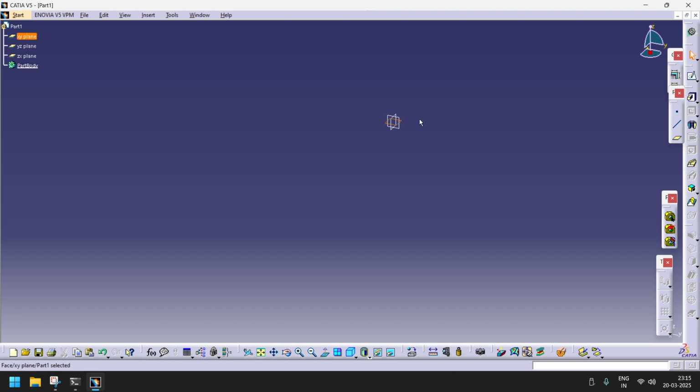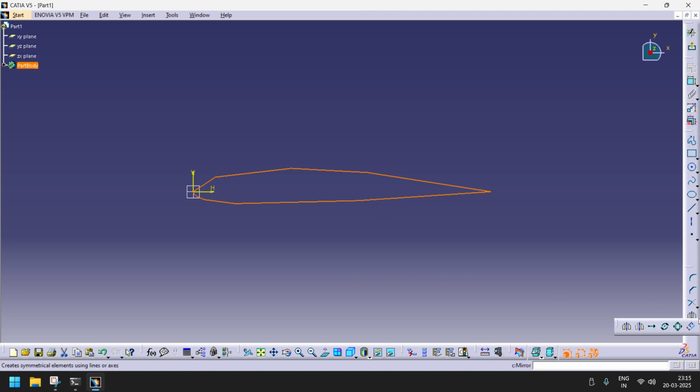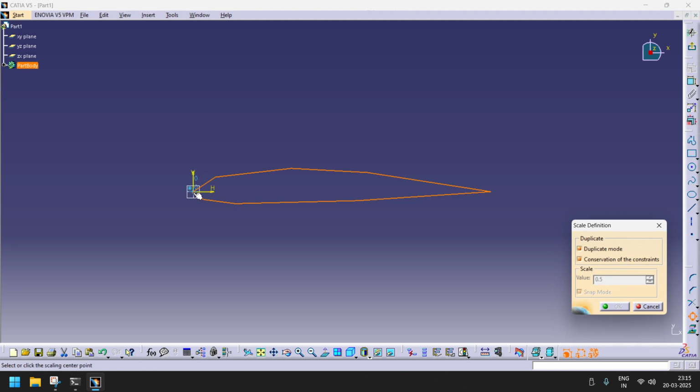So I am going to the sketcher using the same plane. Now paste it. So this is the airfoil extracted from those imported points, and then I can go for the desired length. For example, I am going to extend this for 100 centimeter. As now it is just 1 mm. Maybe just 100 mm I will try. So 100 mm.